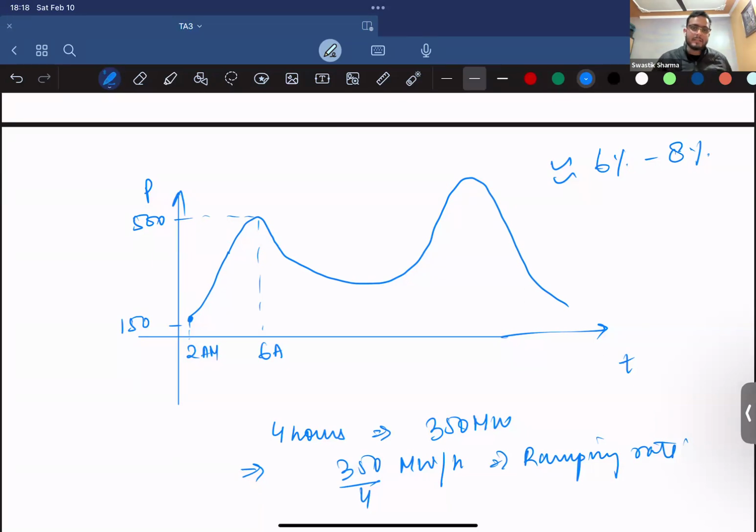The system operators in different places, NLDC, which is the Grid Controller of India Limited, formerly known as POSOCO, asked all the RLDCs, which in turn asked the SLDCs, to keep their hydropower at a minimum threshold, so that when the time comes for proper ramping, they can quickly enhance their ramping capability to survive the whole dip and whole crest and peak. So how did they do that? They asked their coal-based power plants to supply the base load.